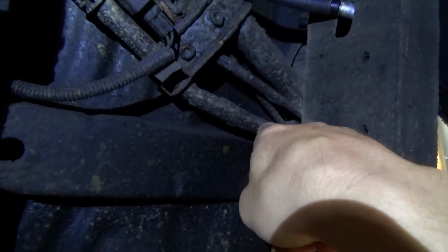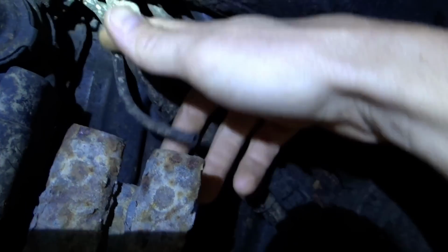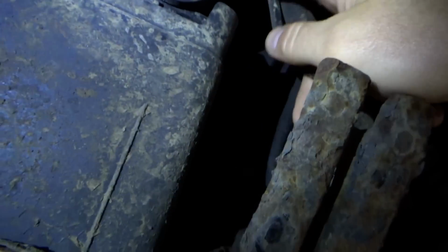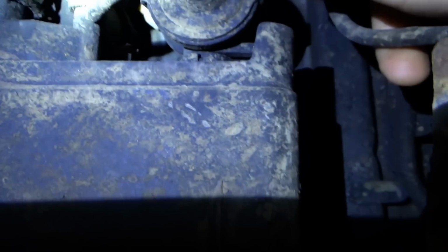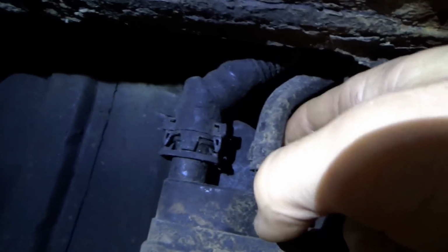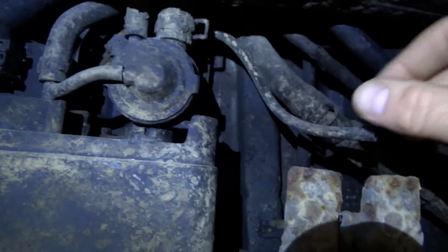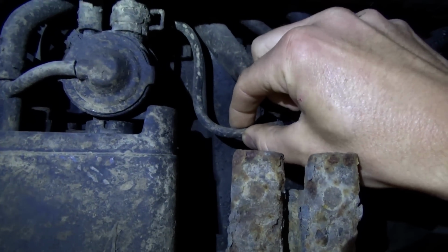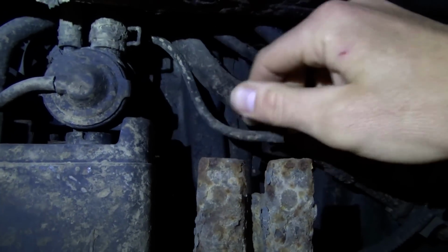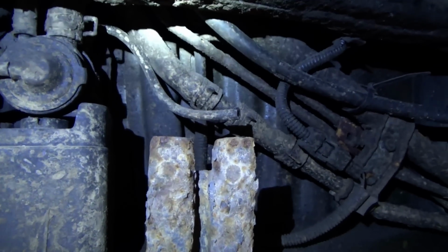Now that is just a fresh air hose with a filter on the end of it, and this is a reference for the tops of these solenoids, I believe. See, there's a T, it goes right to here, and then it tees off and goes to the top of this one. So the tops of those diaphragms have atmosphere going to them. So it doesn't really matter if this is connected or not for testing, but we can leave that unplugged. Let's do a little more research.